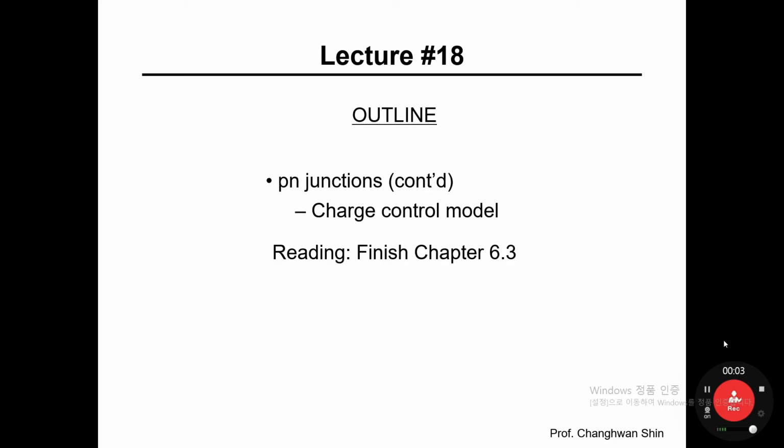Okay, so in this movie clip, I'm going to teach you how to get the PN junction diode equation in another approach. Typically, we take advantage of using the slopes of excess minority carriers in each quasi-neutral region in a PN junction diode. That's a very conventional and typical approach to get to the ideal diode equation. However, in this movie clip, I'm going to tell you there is another approach using the charge control model.